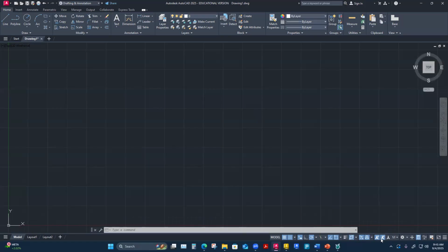So really, the text on my drawing, when I finish, no matter what scale I've had to apply to my actual object on my drawing, I want the annotation to be legible at either 0.2 or 0.125 size on a finished print. So what CAD has is an automatic thing. If I do my text correctly, which does take some thought, I'll have to show you how to do this. But if you input your text correctly in your model space, it'll have this annotative function where it will apply those scales to my text so that my text remains the correct height, but I can try different scales of my object to fit it on my paper. And so these little pinwheel items have to be on in order to do that.